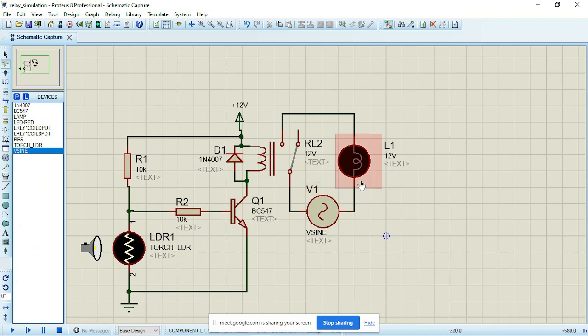So what will happen is that once you trigger this relay, this common will move away from the normally close and go to normally open, and this normally open has already been connected to the other part of your bulb. Looking at this side, the other part of the AC was also connected to this part. So this part is constant. What we need is for this part to be complete, so that the bulb will light. Once you trigger your relay, this other part will be connected immediately and your bulb will come on.